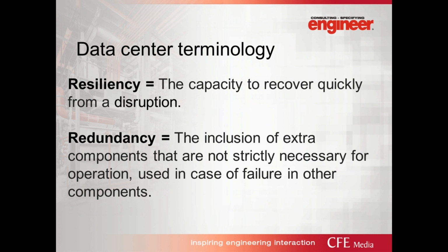So from network trafficking, shifting that traffic to a different site, maybe there's active, disaster recovery backup sites that don't require you to be as redundant with your electrical infrastructure. Things like continuous cooling for the data center. Whether you're number crunching and you have to have maybe some mechanical units on UPS, or you're going to have thermal runaway, or maybe you can have a little bit of downtime on your mechanical system and let it come back for 3-4 minutes. It's all dependent, and understanding resiliency needs is key to the right design.